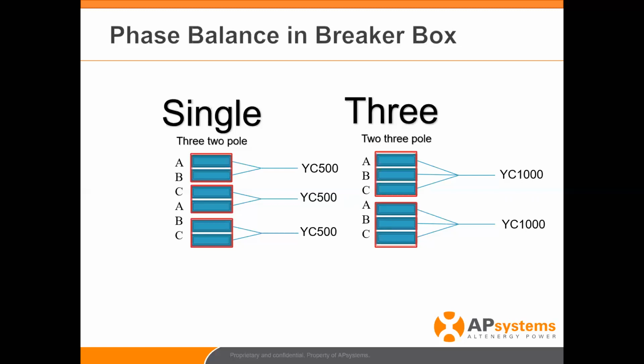Look at the STC. Ask about the PTC. Ask the manufacturer, what is your PTC for this module? Some will tell you, some won't. But again, you can go to the California website, Go Solar California. That's all been done by third-party testing, and it's all published there, all public data.